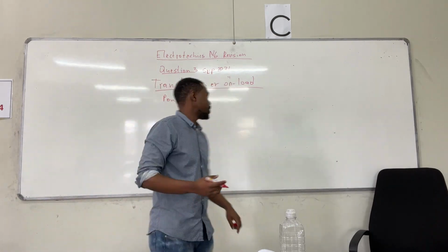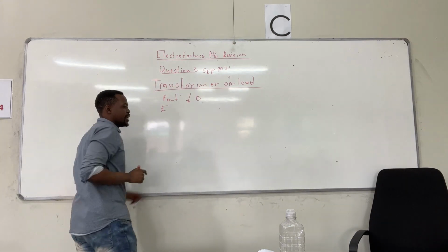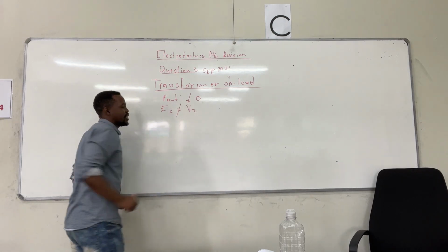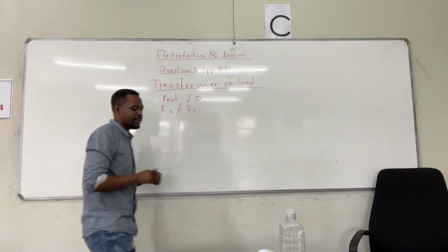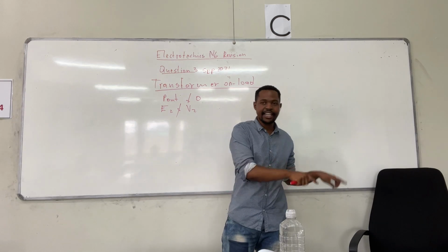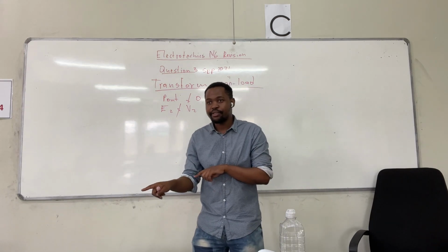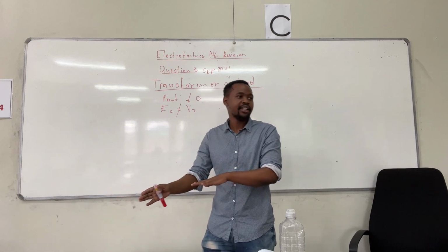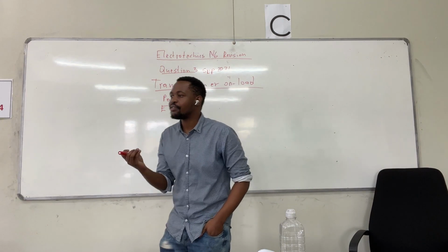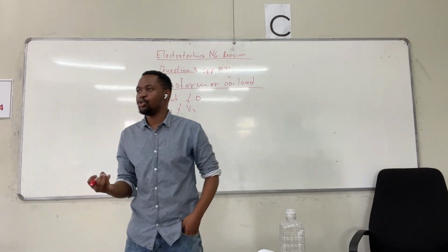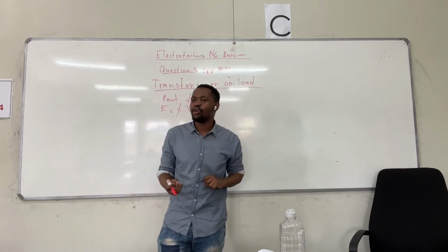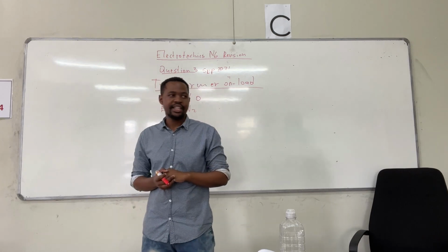And we can no longer say that the back EMF is equal to the terminal voltage. Why can we not make that statement? Because now we have current flowing in the secondary winding, in the secondary circuit. Meaning we have internal what? A voltage drop due to the resistance, the reactance, and the impedance of the secondary winding.